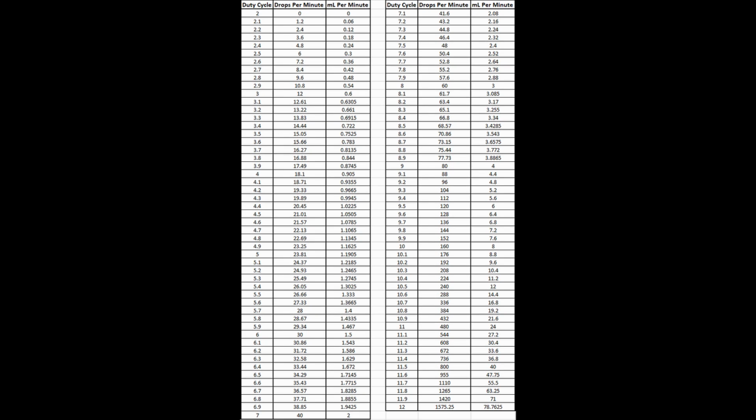The final aspect of this subsystem is the flow monitoring. The initial plan was to use an IR beam break sensor to detect water dripping through the drip chamber, as water absorbs IR light and would have registered as the beam breaking. However, this sensor did not work, as the IR beam is not concentrated enough. This resulted in the beam never registering as broken, no matter how much or little water was passing between the sensor.